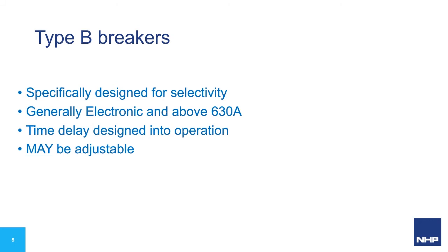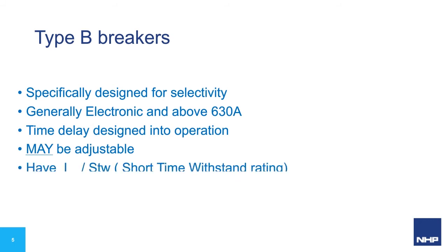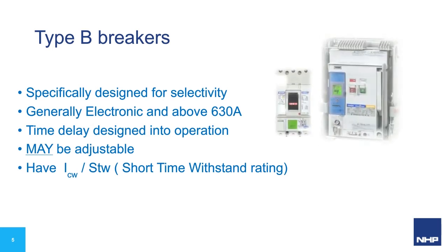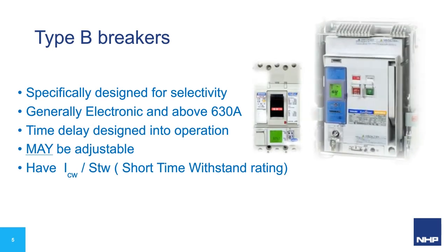Air circuit breakers, generally speaking, are designed and manufactured to hold onto short circuit faults to allow devices downstream to operate and interrupt the faults. The overcurrent relays need to be commissioned and set to appropriate time current coordinate levels to ensure a proper coordinated protection system is in place.